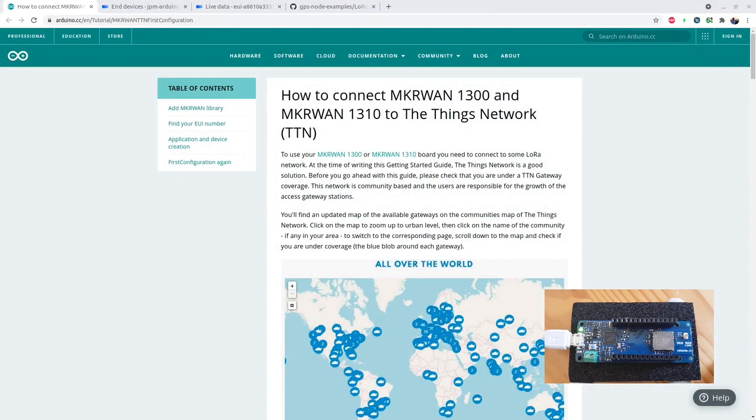In this section, we will use the Arduino Maker WAN 1300 to do a simple LoRa range test. You can however use any other end device as long as it sends uplink messages periodically. To follow along, you need the Arduino IDE installed along with the Arduino SAMD board definitions and the Maker WAN library. If you followed the LoRaWAN devices workshop this morning, you should already have these installed and have your Arduino delivering messages to the T10 console. We will do a quick recap.